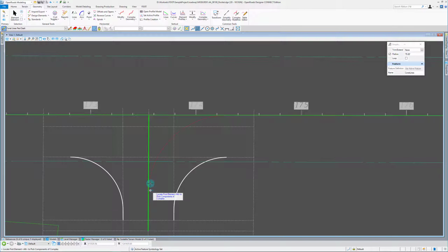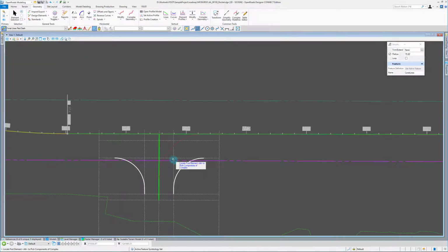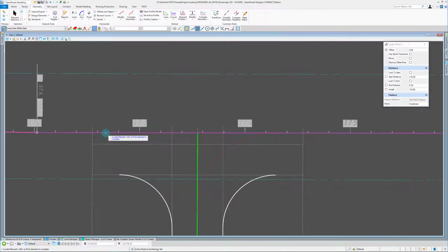That looks like it's setting my stop bar kind of far back, so we might end up changing that a little bit. Not a huge deal. That's something you discuss in design, and maybe figure out if you want to reduce this turn. We'll see what this other one looks like. Maybe we want to reduce it to try and even them up a little bit. So I know this one is just going to be 11 feet.